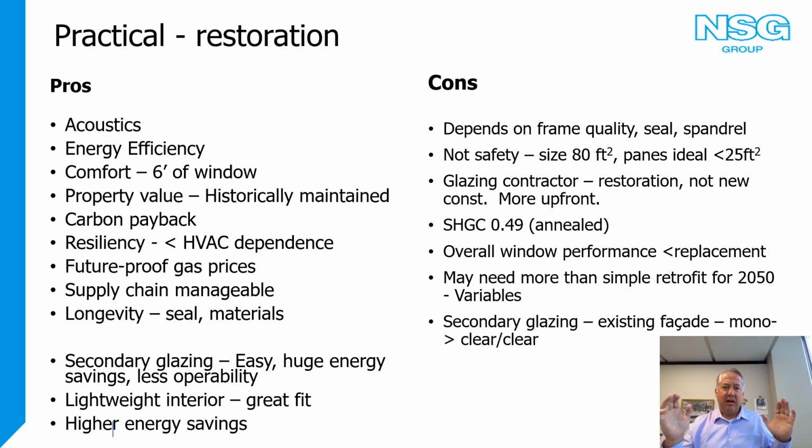In terms of some of the products that we mentioned, even though they're technically available in certain sizes, you may not realistically want those in all those sizes. There's more of a sweet spot, especially when it comes to safety applications. Floor to ceiling stuff tends to have to meet safety code. Some of the annealed VIGs aren't going to meet that. So even though you can make the annealed VIGs in up to, say, 80 square foot panes, the sweet spot on your projects is maybe more the operable windows, the stuff that's not above 18 inches and is maybe smaller than 25 square foot. You start to have to look at all that.